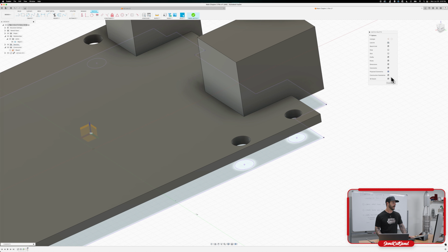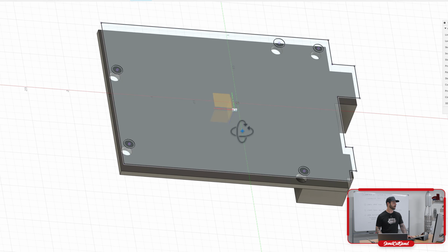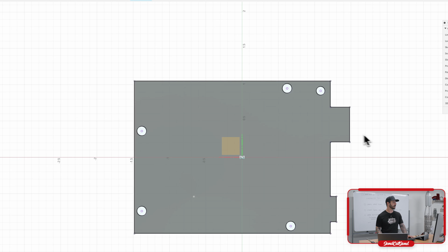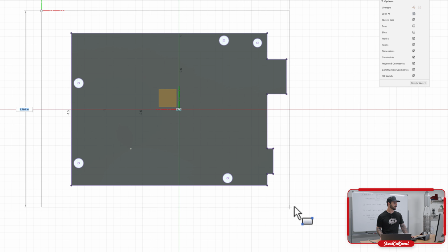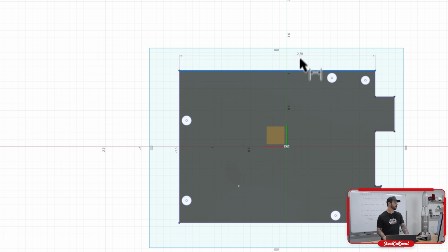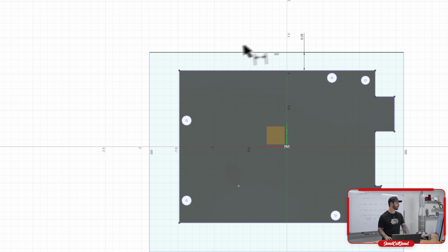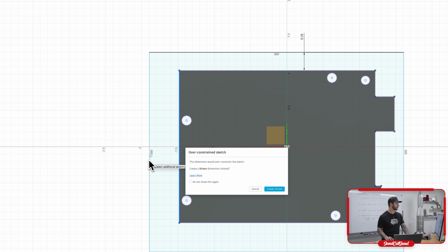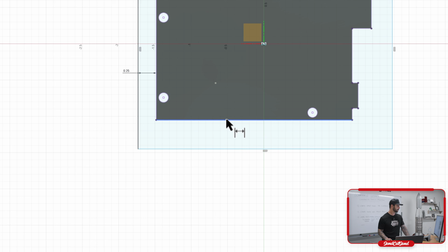Clicking OK on that, we're still in our sketch, but we have a nice proper duplication of our Arduino down there. Let's go ahead and create a rectangle that goes around the Arduino. This is going to be the outside of our box. Now we're going to use the Arduino edge to do an offset of about 1/4 of an inch around the outside. This will be a nice little spacing that we can have here. Clicked on the wrong thing there. Now we can create that spacing that we need to have a little bit of a shell around the outside.